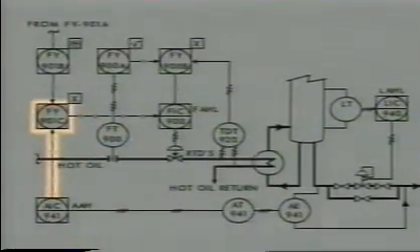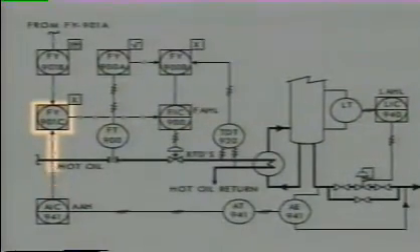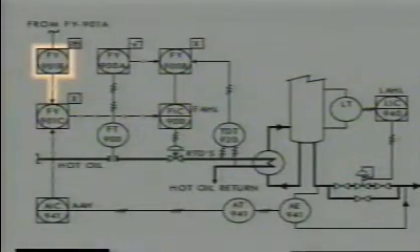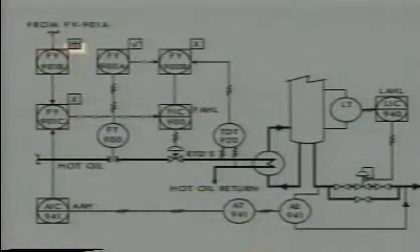The signal from the analysis controller is received by multiplier function 901C. The other input to this multiplier function is generated by flow computing function 901B. This is a time-oriented function that is part of a shared control unit and not accessible to the operator.